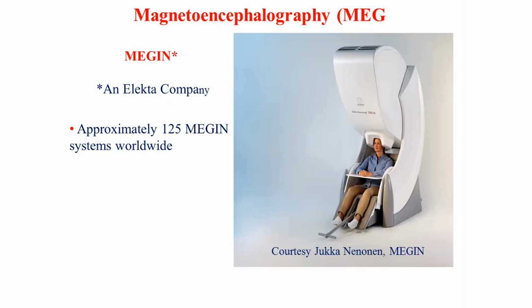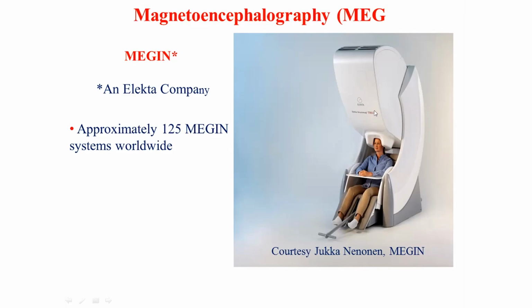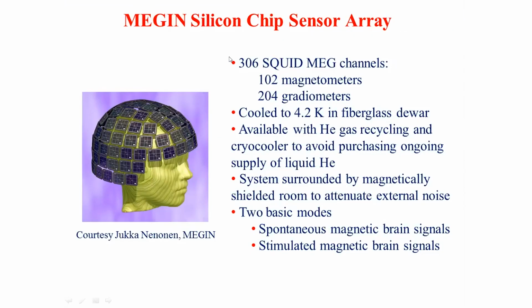And then one of my favorite applications is magnetoencephalography. This is a system to measure magnetic signals from the human brain. It enables one with incredible sensitivity to see what's going on in the brain. In that kind of system, there are no fewer than 306 SQUID channels, and it has to be in a very magnetically shielded room because it's looking for these tiny signals.